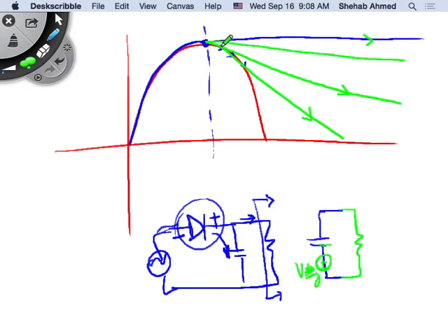Right? So this point, initially the point theta was up here. Theta was equal to pi over 2 initially. Theta is where the source voltage and capacitor voltage slopes start differing. If the capacitor voltage stays equal to maximum value, theta is equal to pi over 2, because right beyond pi over 2, source voltage starts to go down. Its slope is going to change versus the capacitor voltage slope. Capacitor voltage slope will still be 0, right?